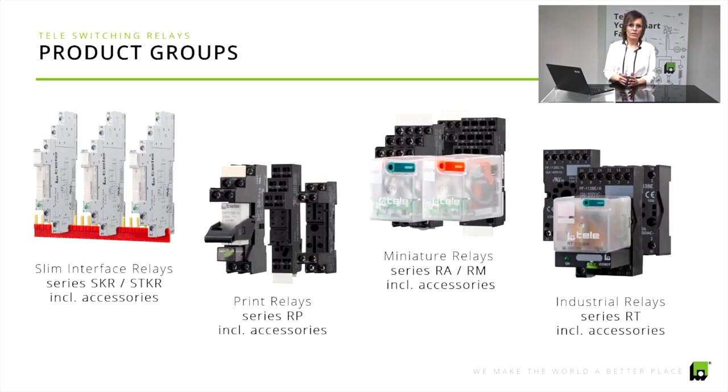On the far right, you can also see samples of industrial relays, the so-called RT series with its respective accessories. These are equipped with 8 or 11 pins and can also be used with the multifunction timing module, which benefits you by providing a timing relay with more outputs and enabling higher switching capacities.